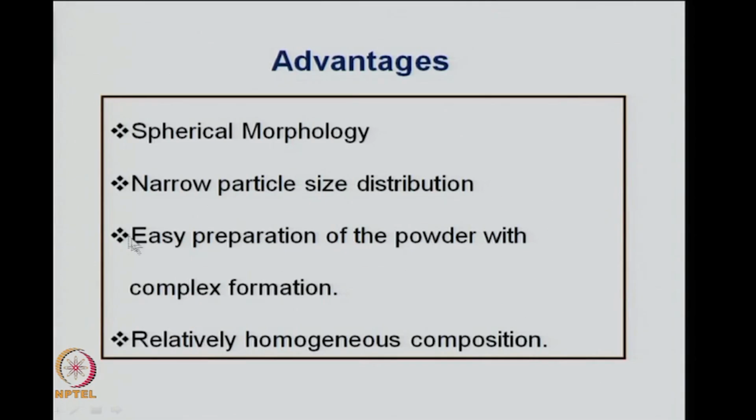Now, the advantages are, in most of the spray pyrolysis processes, if you choose your starting precursors properly and you choose your solvent also appropriately, then you end up with particles with spherical morphology with reasonably narrow particle size distribution. The process is quite simple, and ultimately it is a good product for minimal investment.